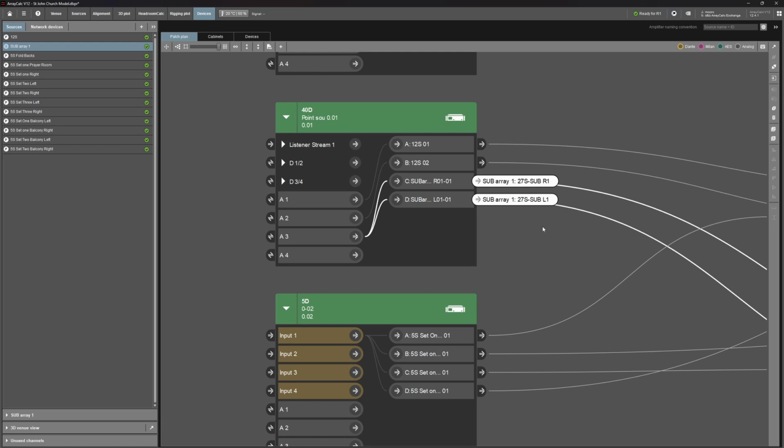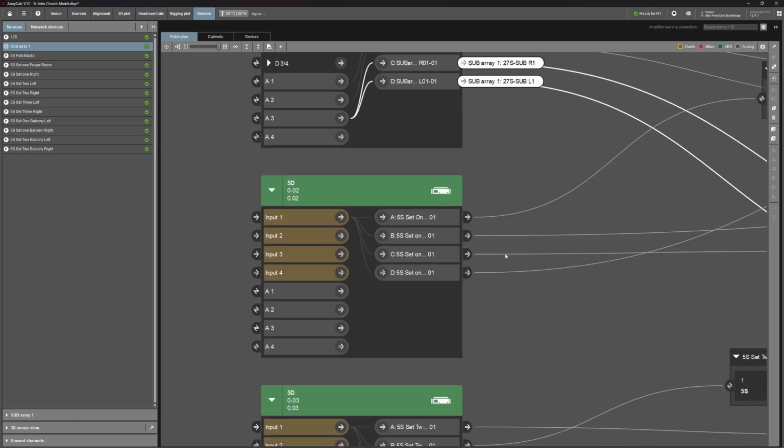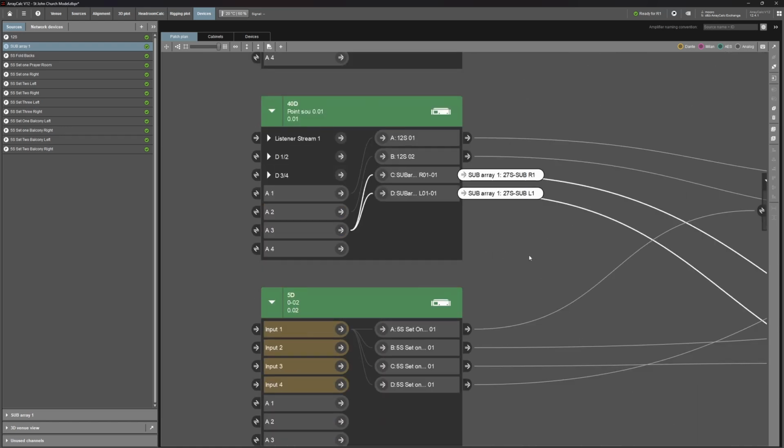I think I designed it to be analog in. So that's why it's using 3 different analog inputs. The first 2 being left and right, and the third one being a sub input. And that'll be 3 buses coming off the sound desk, as this project was designed to have a proper sound desk with left, right, and a mono send to keep it easy and distributed, and the sub level can then be controlled a lot better.